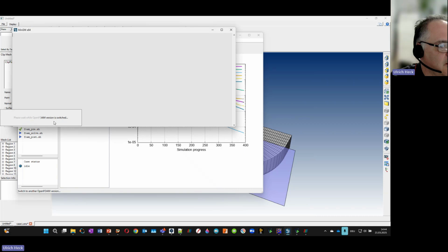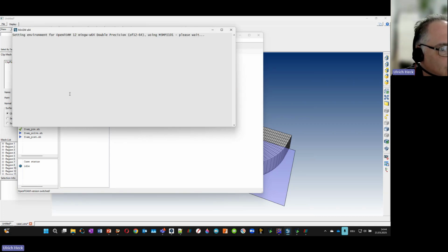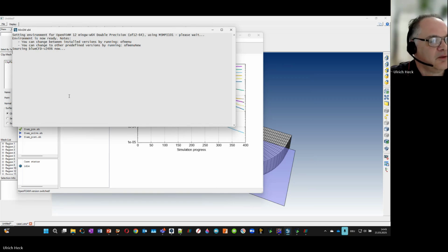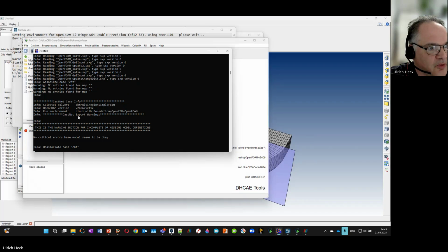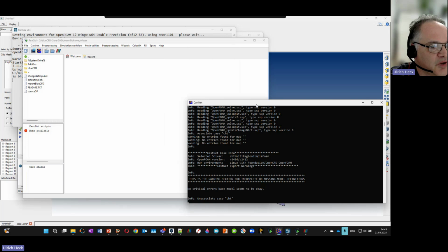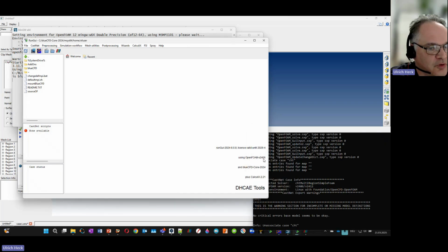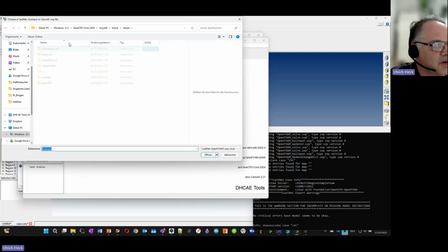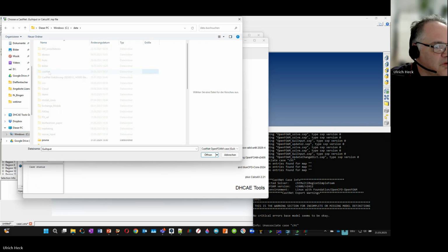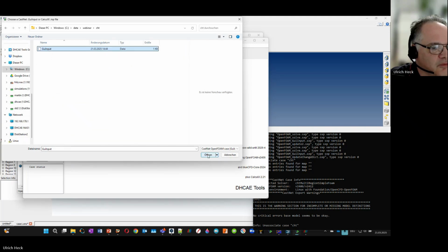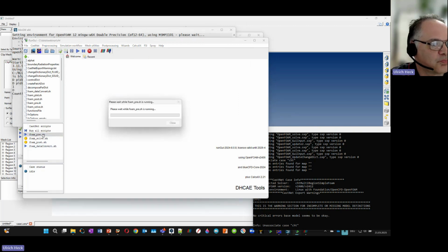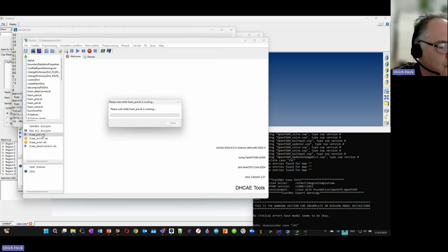And then I get a new window of RunGui where another OpenFOAM version is sourced. So let me see the Explorer. Okay, I see the export is fine. And also in my new RunGui window, I see that OpenFOAM 2406 is used. I go to my directory where I exported the case. Then again, I execute this prescript, and this generates the case structure for my conjugate heat transfer case with all the subdirectories that I would like to use.